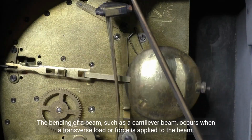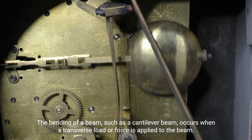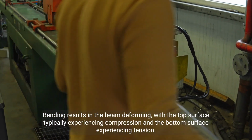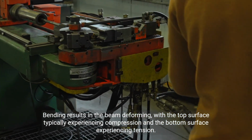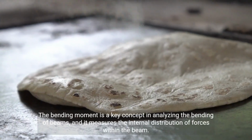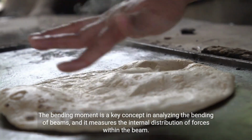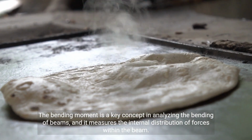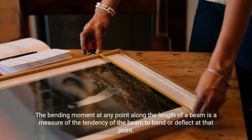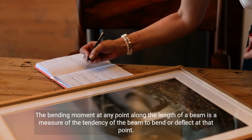The bending of a beam, such as a cantilever beam, occurs when a transverse load or force is applied to the beam. Bending results in the beam deforming, with the top surface typically experiencing compression and the bottom surface experiencing tension. The bending moment is a key concept in analyzing the bending of beams, and it measures the internal distribution of forces within the beam. The bending moment at any point along the length of a beam is a measure of the tendency of the beam to bend or deflect at that point.